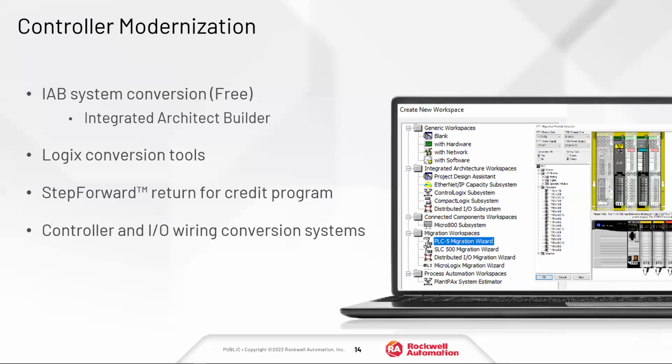And with respect to modernization, there's about 3 different wizards built into the product that step you through different migrations of controllers. So there's a PLC5 migration tool, there's a SLC migration tool, there's a MicroLogix migration tool. And so that's really where you want to start when you're looking at a controller modernization.